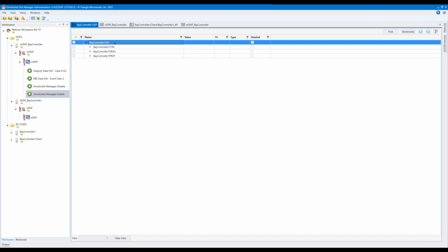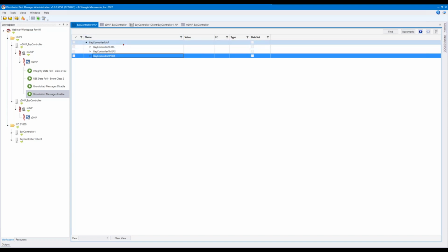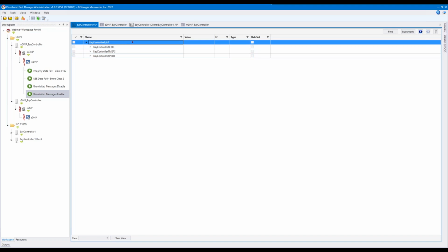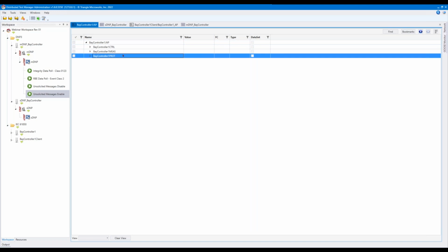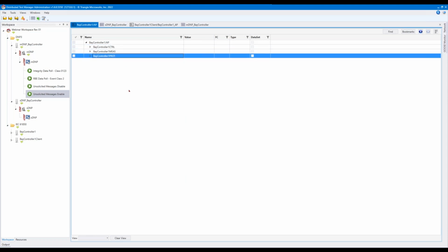So at this top level, we see where it says Bay Controller 1. So this is my physical device, or IED. As I expand that out, I see 3 different logical devices at the next tier. So if we could imagine a protective relay that you might have in a substation, that is represented by this top rung or trunk, but as we go down, the first three branches are the logical devices in that. And in this case, they've been used to break up the different functions logically that this device might perform. So those would be control, measurement, and protection.